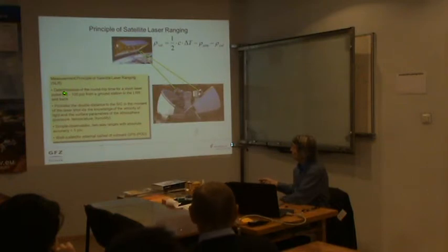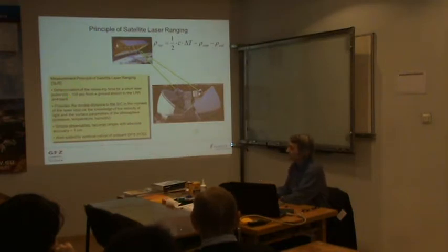So in our times, I should maybe modify it from time to time. The laser pulse width is in the order of a few tens to 100 picoseconds. The shortest pulses used for laser ranging for the moment are 10 picoseconds, and they will not become much shorter, at least within the next 2-3 years. But as you have heard a few days ago, there are ideas, in a project governed by the University of Riga, to use femtoseconds for laser ranging to satellites. It would open a fully new field of research, but it is not so simple.